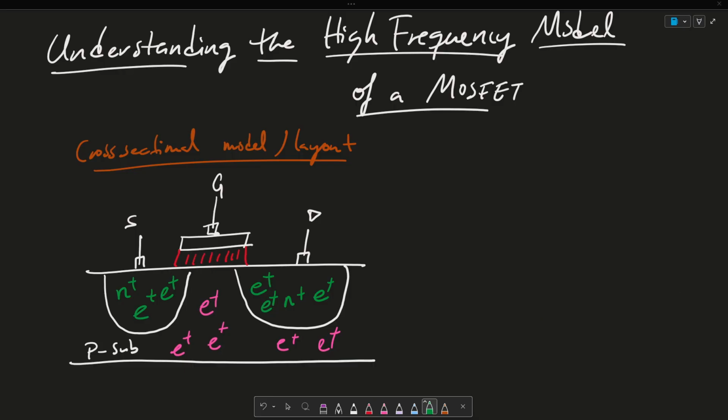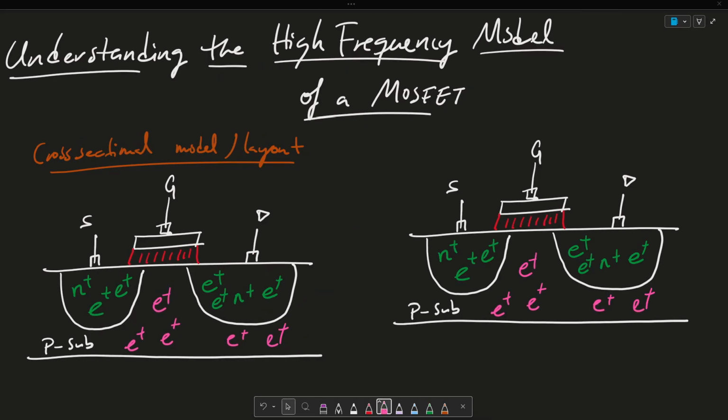To understand quickly the working principle of the MOSFET, I'm going to redraw this image to the right-hand side and show how that works. So essentially, how a MOSFET works is when we connect the gate to a battery supply, you can imagine that I get a whole bunch of holes or positively charged carriers coming in and settling at the plate of the gate. It pushes these away. Okay, so these go away or they get rejected. So now they're on the bottom here.